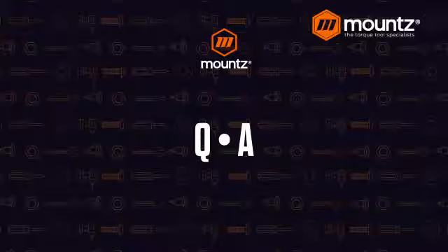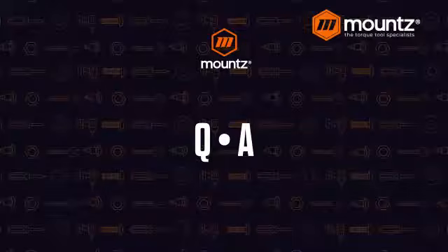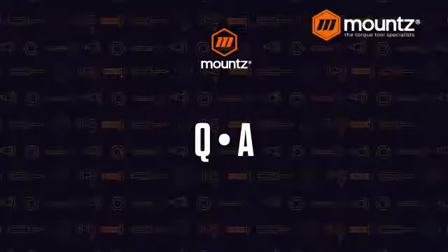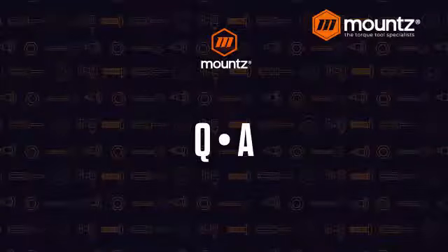So either a small butterfly impact pneumatic tool, you would not want to use that on there because there's not really any torque control. And then the hammering that happens could damage the sensor. So you can use it on just about every air tool except for an impact tool.